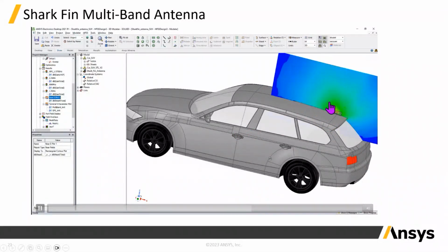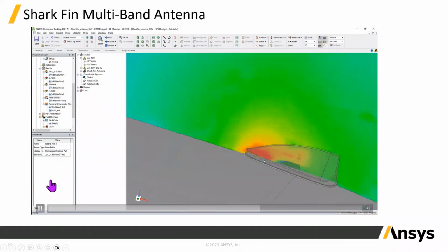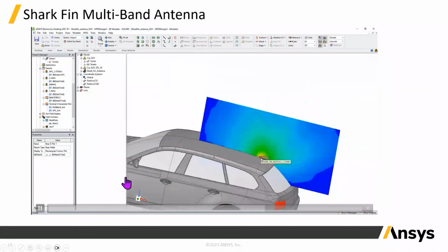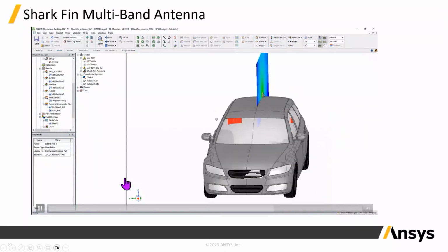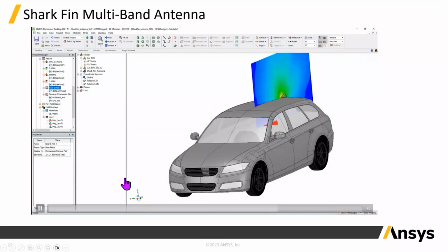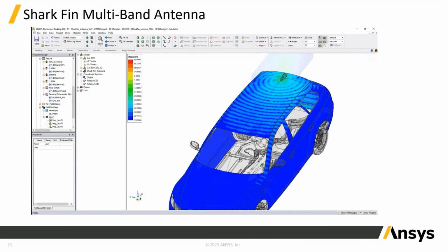You can integrate everything and see the far field radiation, the near field, the surface current, everything. This can be nicely visualized and validated, and its results are well correlated against measurement with different customers. So you can see the surface current which is generated on the vehicle when the antenna is radiating. You can animate it and see how the surface current is propagating over it.